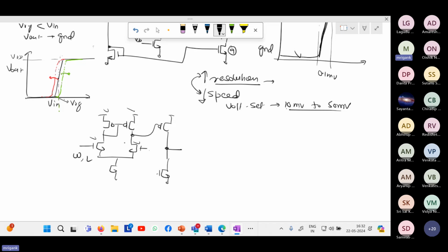For analog circuits, this kind of matching of the devices is important. From the fabrication point of view, the way we do the physical layout of the devices, we try to physically match them. The physical structure of the devices should be very well matched, so that the offset is reduced. And the larger the W and L, the smaller the effect of mismatch, because the randomness reduces.